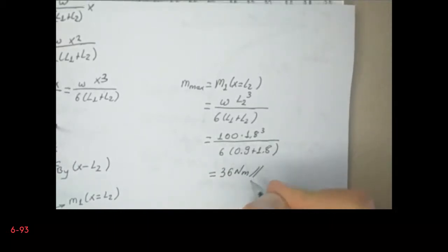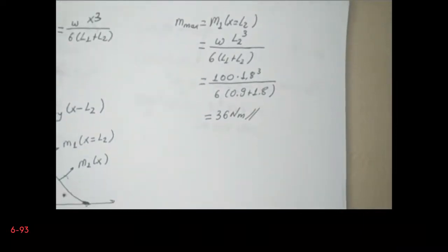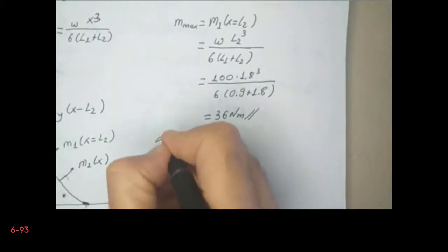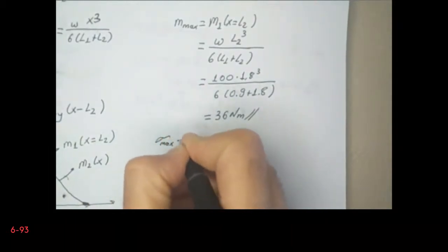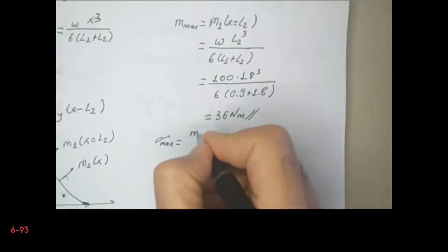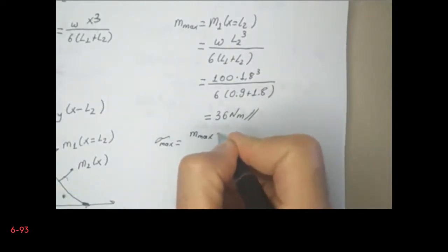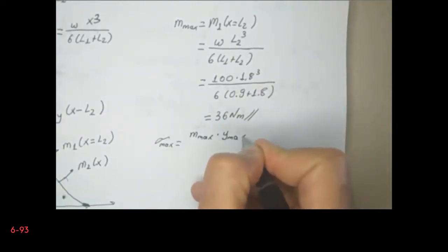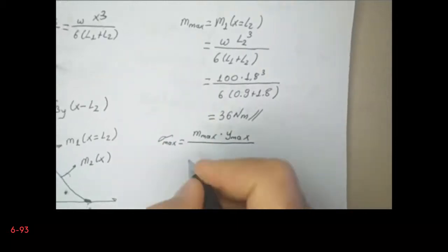Now we know the bending moment. The next thing is to calculate the maximum stress. This is M max multiplied by Y max, divided by I bending.